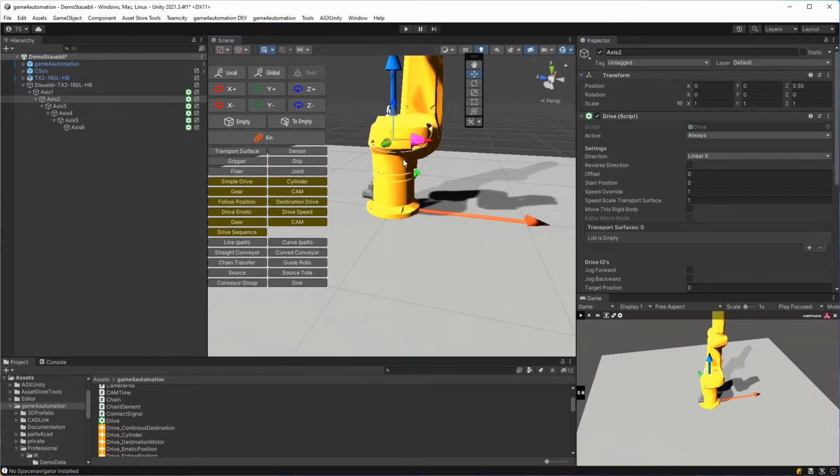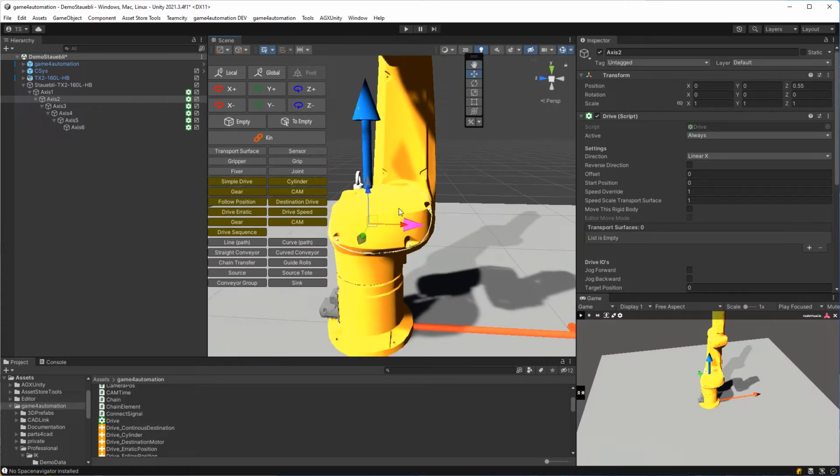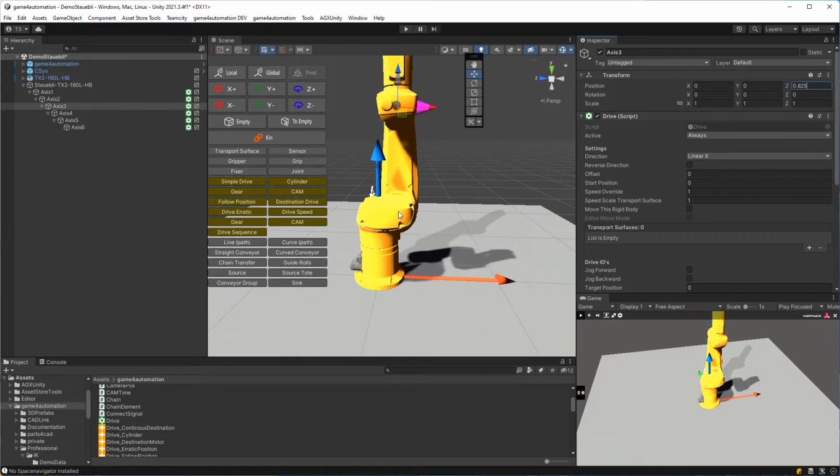And for getting the rotation point in the X direction, we are taking out of the technical design this 150. Not Y, it needs to be the X, 0.150. So by that, we defined axis 2, and we'll continue this for axis 3. Looking into the data sheet, it's in the height 0.82 in relation to 5 in relation to the axis 2.